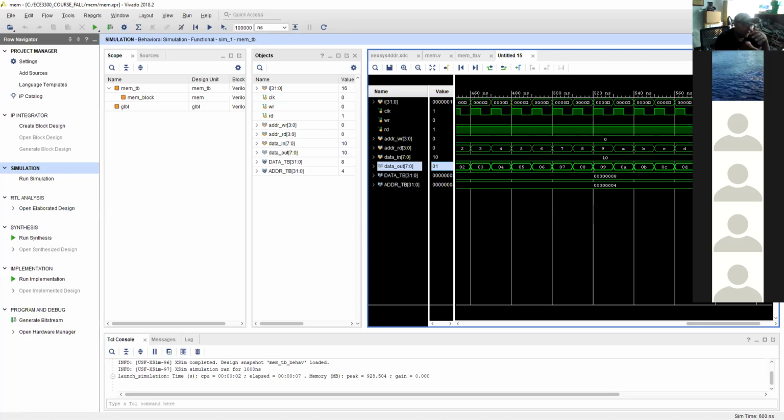And then we talked about the timing. We specifically talked about the skew, synchronizations, the two rules we have to follow, whether the positive skew versus negative skew. Positive skew, we said the setup time will be improved while the hold time will be degraded, and vice versa for the negative skew. We said the setup time will be affected in a negative way while the hold time will be improved. Then we talked about the accessory.